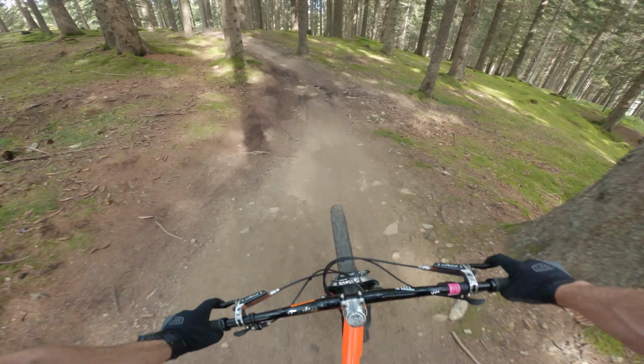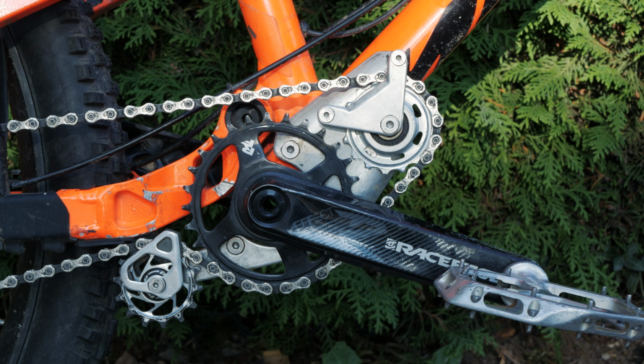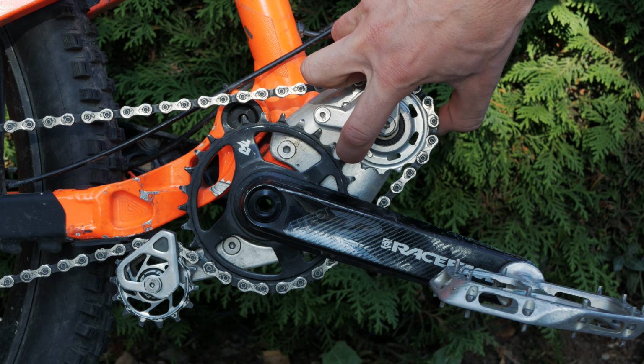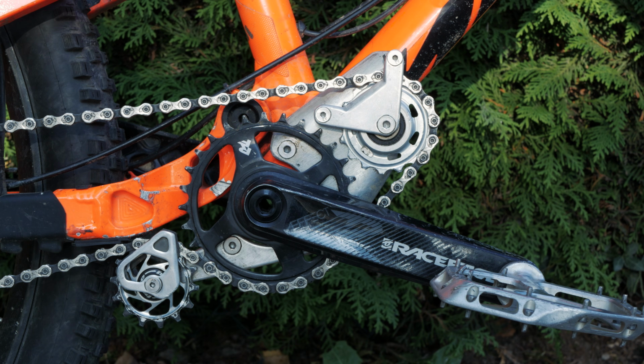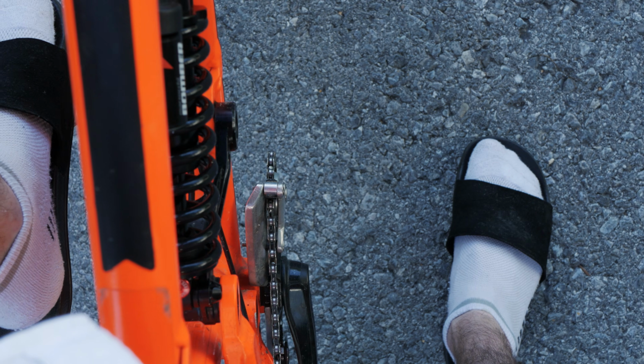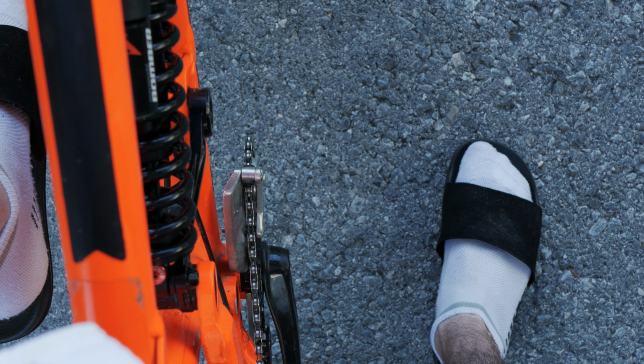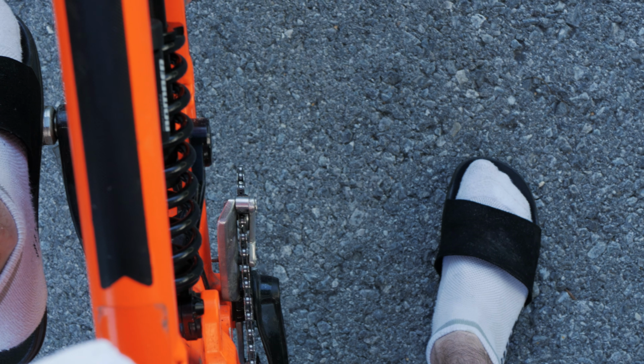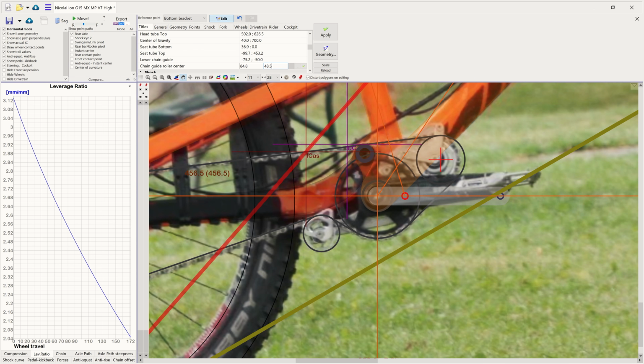There is one issue though. I may have placed the idler pulley a bit too close to the chainring on my current mounting plate. Under heavy pedaling, the idler gets bent outward and the teeth make contact. My brilliant workaround up to this point was to avoid hard pedaling, but I figured at some point I should make a new plate with an adjusted idler position.